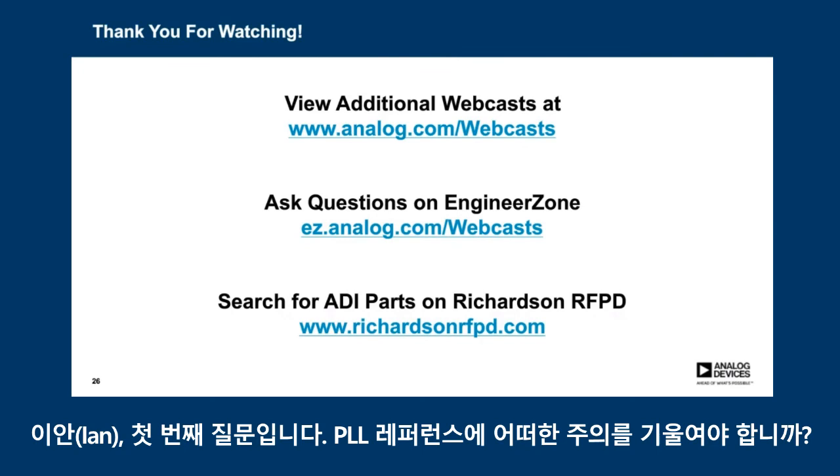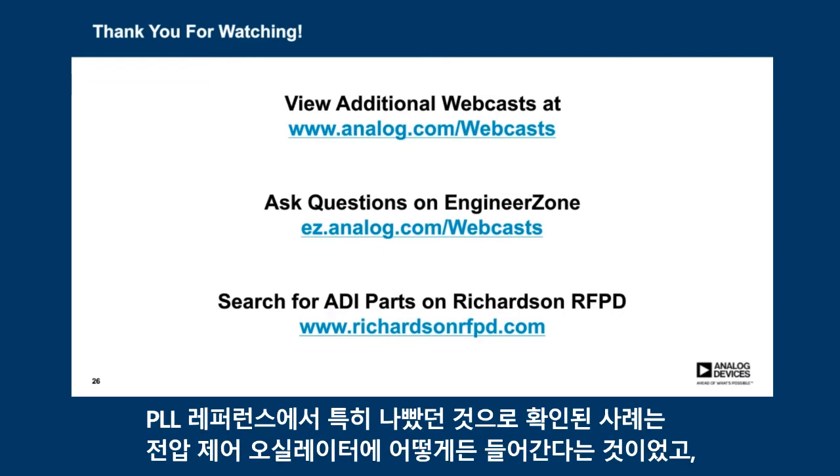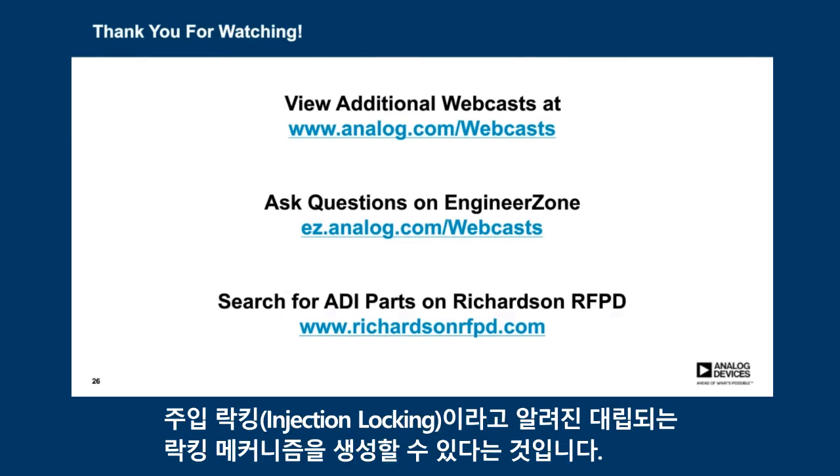Our first question for you, Ian, what care should be taken with the PLL reference? The biggest care to be taken with the PLL reference is that it isn't routed too close to the VCO. The one case we identified, which was particularly bad for the PLL reference, is one where it can somehow get into the voltage-controlled oscillator and create a competing locking mechanism known as injection locking.